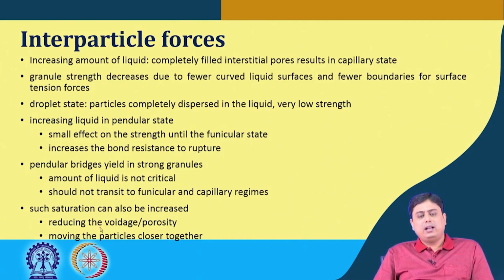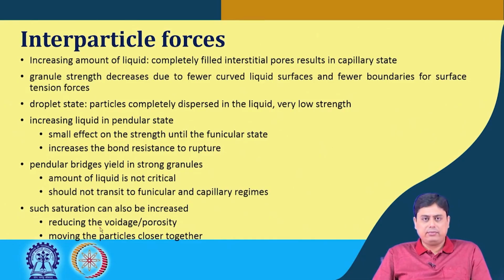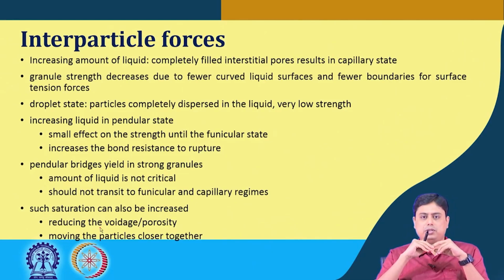It has been seen that an increase in the amount of liquid in the pendular state has only a small influence on the strength until it moves to the funicular state. If it is in the pendular state and you increase the amount of fluid, it increases the bond resistance to rupture.